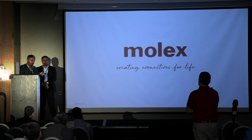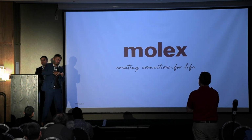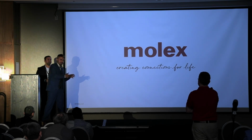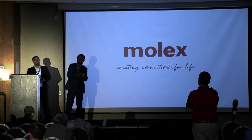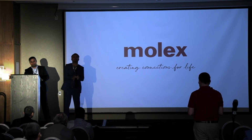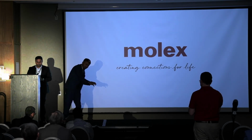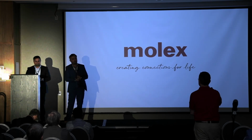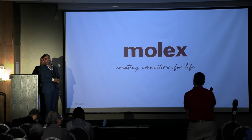Just to add one point, right? Correct, but sometimes since the chipset is on the PCB, it will be switching continuously at some particular data rate. So some weightage has to be given to a good layout of a PCB, because normally the noise is injected from the PCB, which goes down the cable end. So PCB is also very critical, Gustavo. Thank you.